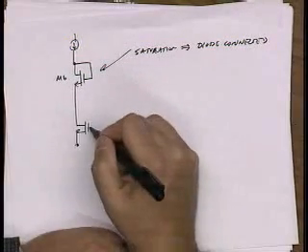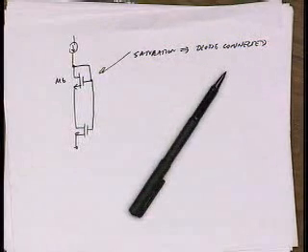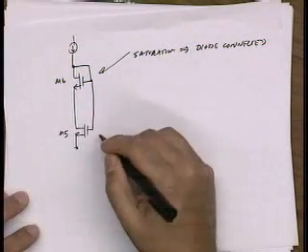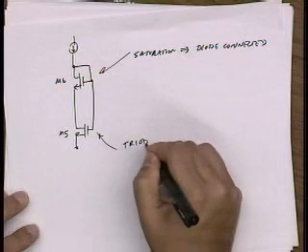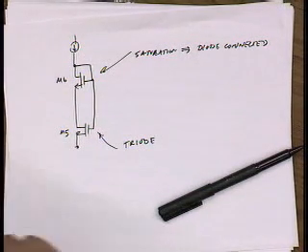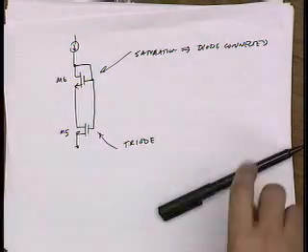And then this device, I'm going to bias it up with the same gate voltage and connect the drain to the source of M6. And the claim is that this device is in triode. Why is that? Anybody have a good explanation for that? Sang, you want to? So the top device is in saturation, the rest of the channel is across M5, which has to be in cutoff or triode. Triode, yeah, exactly. That's right.